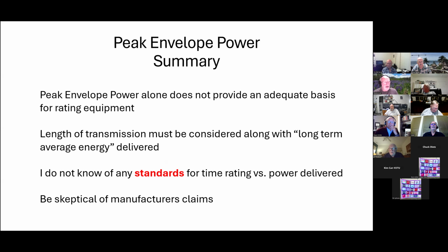There's a lot of talk about duty cycle and that sort of thing. I could not find any standard for duty cycle related to RF power. I looked in all kinds of books and all kinds of online information to try to find that. I see people calculate it different ways. Some people will tell you that an FT8 signal has 100% duty cycle, and some will tell you it has a 46.5% duty cycle. It depends on what you take as the time base for the duty cycle. So duty cycle really is too ambiguous to be very meaningful.